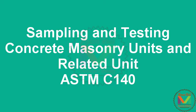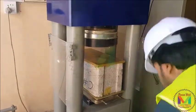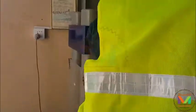Position of specimens: test specimens with the centroid of their bearing surfaces aligned vertically with the center of thrust of the spherically seated steel bearing block of the testing machine, except for special units intended for use with their cores in a horizontal direction. Test all hollow concrete masonry units with their cores in a vertical direction.